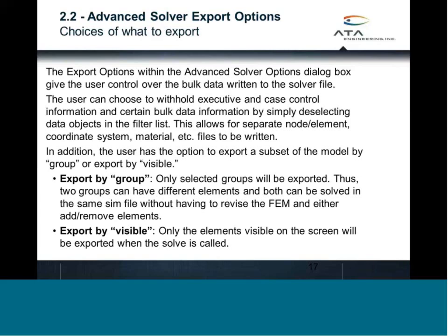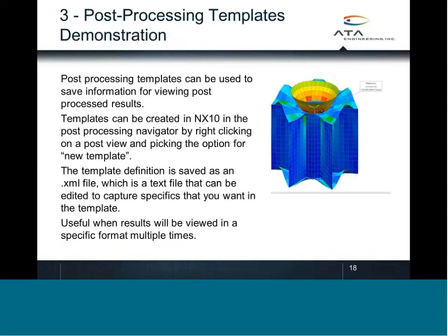Now, for our third and final demonstration here, I want to show you what post-processing templates are all about. Now, before I show you the demonstration, let me just give you some background and overview here so you understand the utility of these. What templates do is they save all of the view configuration settings and options that you're using in the visualizer to post-process results. So if you change the scale on a color bar, you change the units, you change the deformation scale factor, you can